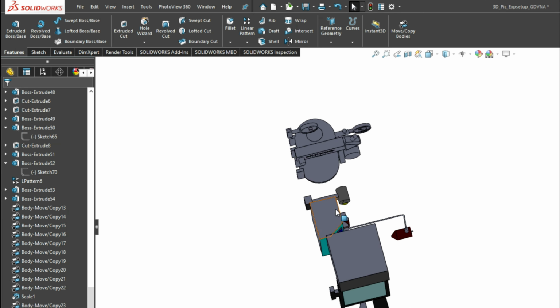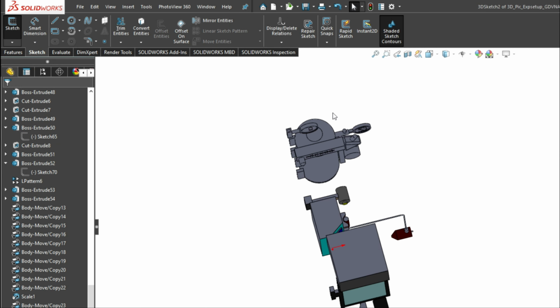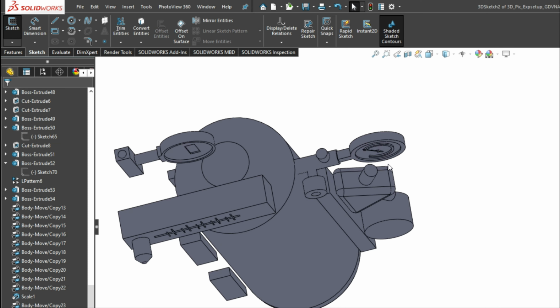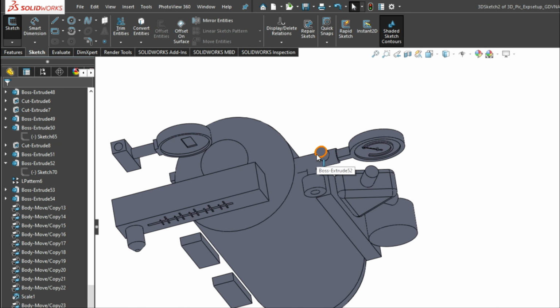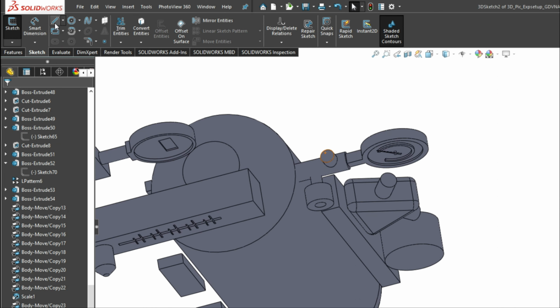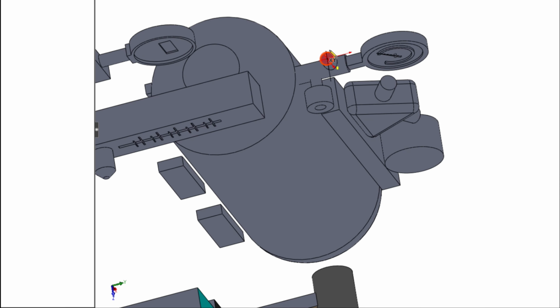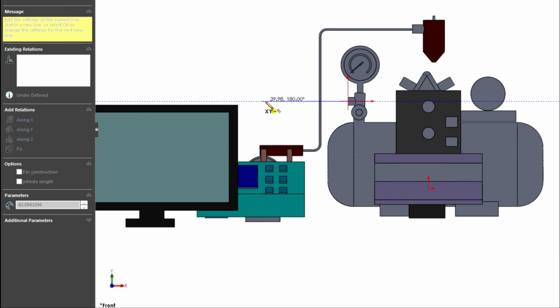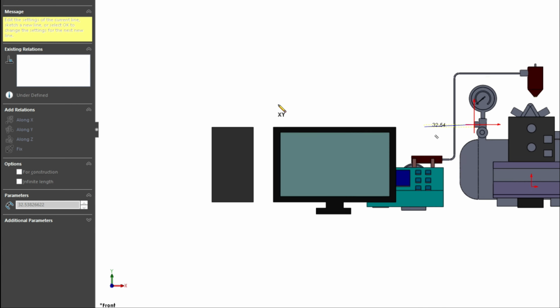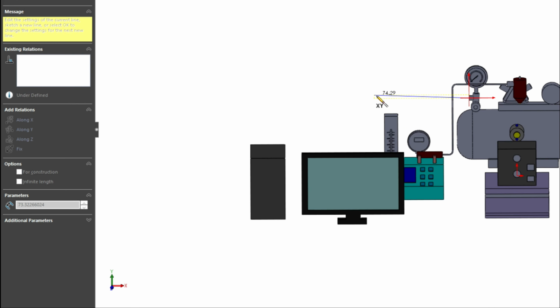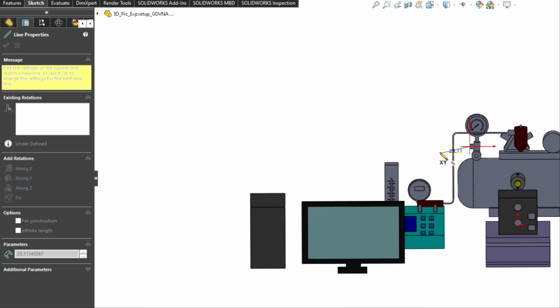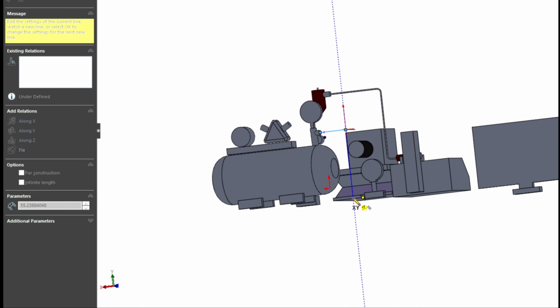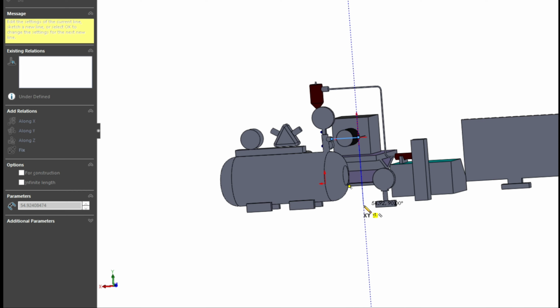Now I will demonstrate a slightly more complicated 3D sketch and swept feature. Go to sketch, 3D sketch, and you have to connect this part to a different part of this setup. I will again use the straight line for demonstration. Here again you can choose a different axis or particular plane where you want to work. I will choose the dimensions so that my experimental parts look connected, but you can choose the dimensions according to your requirement.